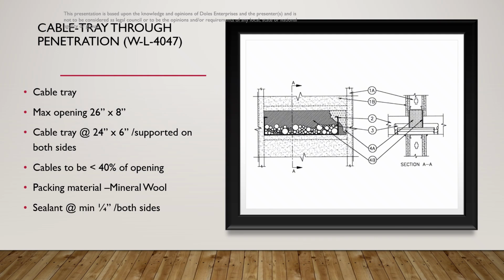For cable tray penetration through a gypsum board wall, the framing of that entire opening must be completely framed in, and then the application can begin. The UL system sheet should be carefully reviewed. This is for cable tray installations. There are very specific limitations for these type applications.